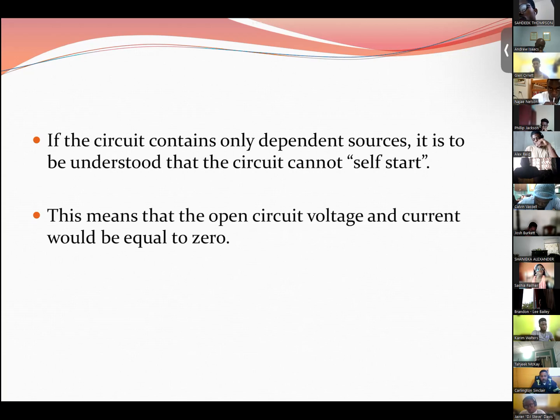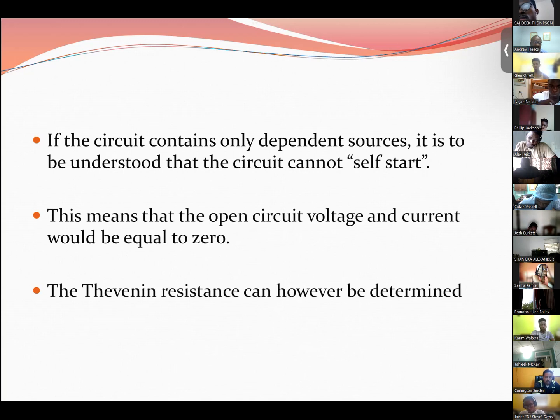However, we can calculate the Thevenin resistance, which is the same thing as the Norton resistance. And all we're doing here, students, for lack of a better word, is to measure the resistance of the circuit with the dependent source being present. That is done by applying the same principle on which the ohm meter works.